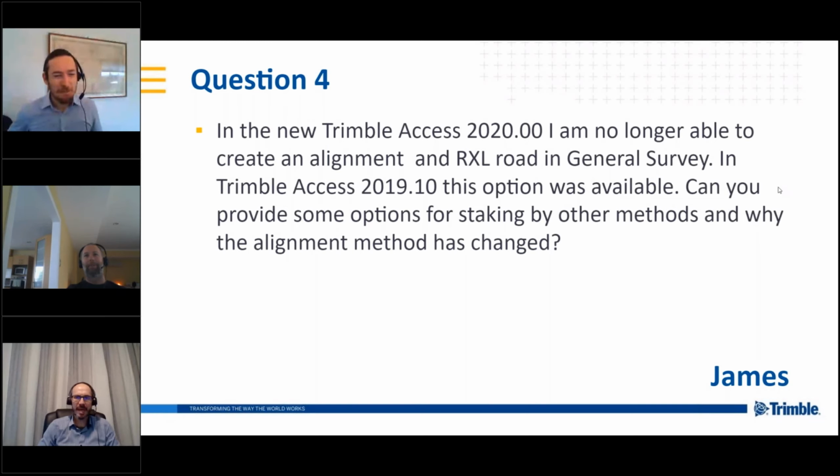Yeah, so they'd like the option back. This is something that we'll pass on to the product manager. However, I'll just explain with the new functionality in Trimble Access 2020. As I think I mentioned before, we can now stake polylines directly without the need to create an alignment.